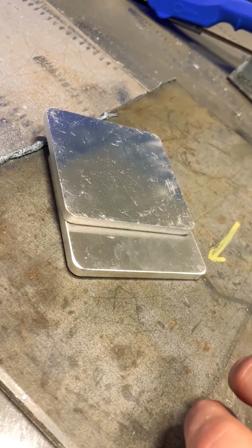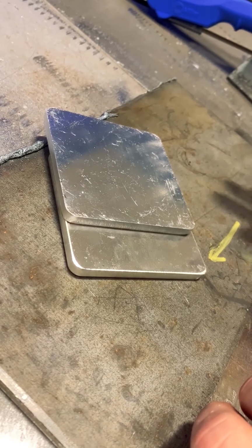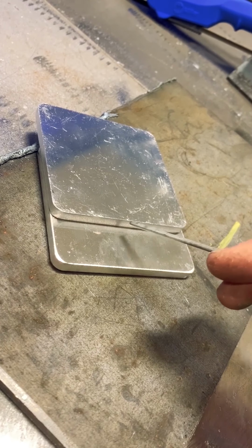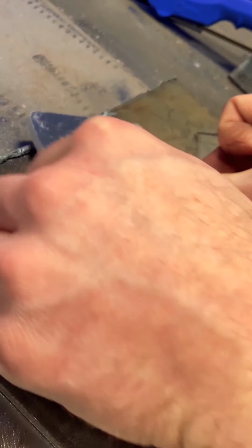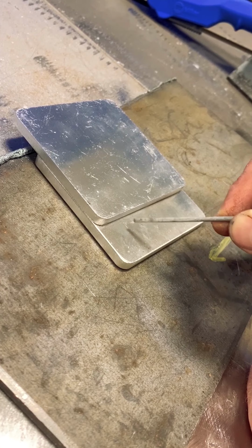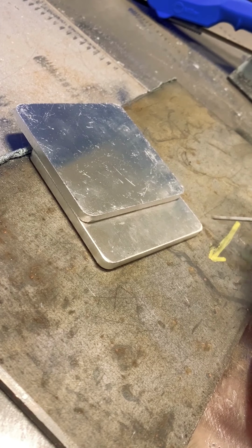When I say waffled, I mean this will identify folks that have bad eyesight, which I find is the number 1 culprit that people have an issue with placement on joint. Placement on joint is going to refer to how my electrode is positioned on the part. In this case, I'm using a tungsten rod as a pointer. But if I have my placement on joint favored too high or too low, I'm going to get an undesirable weld profile because of that.